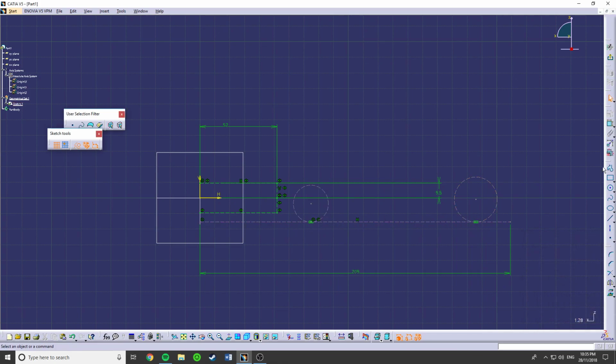Now, when you use the quick select option, so you see the blue lines that are locking to various places, these are kind of like guidelines, and if you bring it out so it's touching the line, it will automatically generate a tangent, but in this case you can just do it by clicking the button up there when it appears.